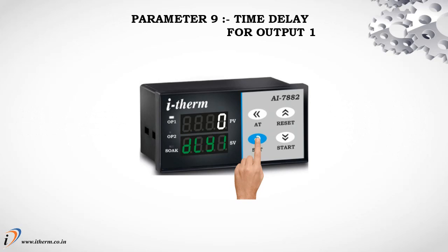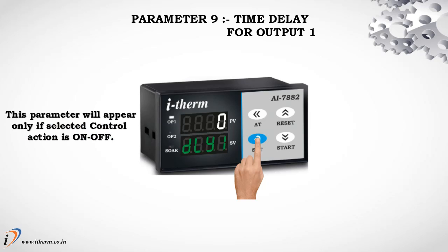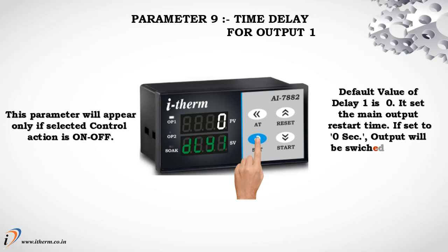Parameter 9, Time Delay for output 1. This parameter will appear only if the selected control action is on-off. The default value of delay 1 is 0. It sets the main output restart time. If set to 0 seconds, output will be switched without delay.